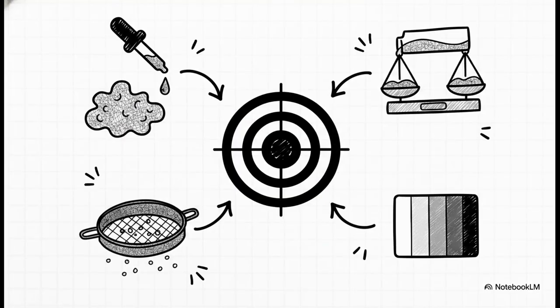Let's distill that overwhelming table down to the essential tests that actually matter for quality control. The standard strictly mandates testing for iodine absorption number and oil absorption number, or OAN for short. These help establish what the standard calls target values, which are the exact specifications that producers center their entire manufacturing processes around. Then, there are typical values established for things like tint strength and pore density. And they don't mess around with impurities either. Sieve residue absolutely cannot exceed 1,000 parts per million of 45 microns, and the amount of fines in a bulk shipment, that's capped at a strict maximum of 7% for most grades.